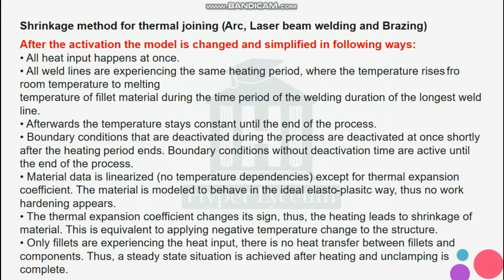After the activation, the model is changed and simplified in the following way. All heat input happens at once. All weld lines experience the same heating period, where the temperature rises from room temperature to melting temperature of the fillet material during the time period of the welding duration of the longest weld line. Afterward, the temperature stays constant until the end of the process.